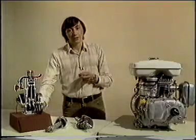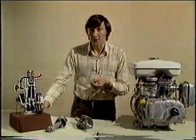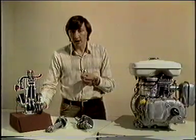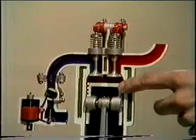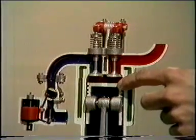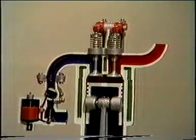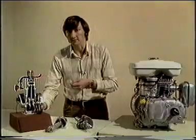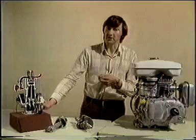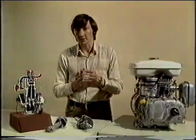Well, if you're not familiar with a four-stroke cycle, that may all have seemed a bit complicated. Certainly I went through it quite quickly. I don't want you to worry too much about it. What I do want you to grasp, though, is that at this point in the cycle, there is virtually no difference in the pressure on the top of the piston to that of the atmosphere. So we have no significant pressure forces acting on the piston. And that's why I chose to do the analysis at that point, because I'm really only interested in the forces which are required to accelerate the mass of the piston.